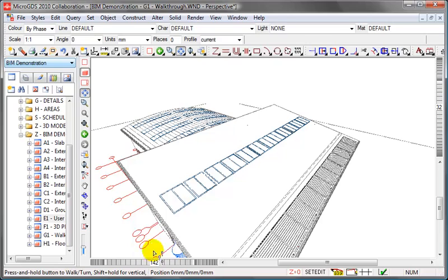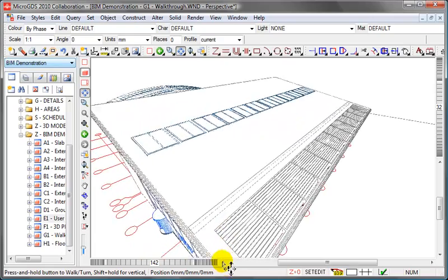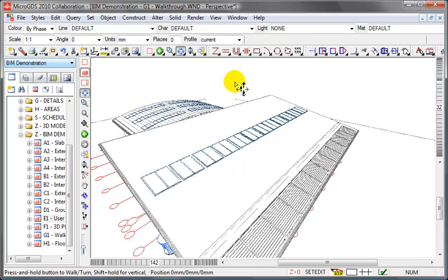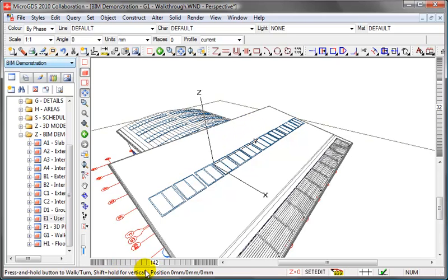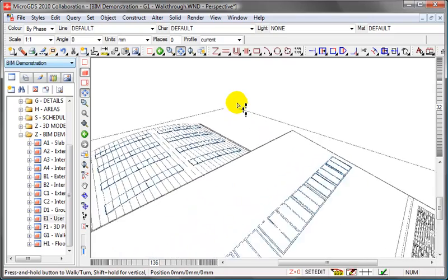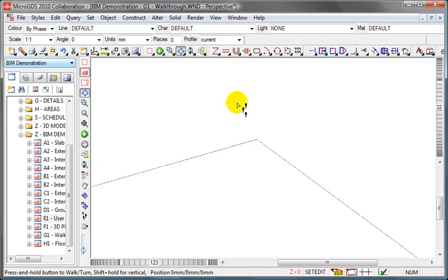And there are modifiers for this command. So if you hold the shift key down and you move the mouse down, you go lower. And if you move the mouse up, you go higher. And there are other options as well. One that's not visible because we're working with a smaller window here for the demonstrations. You can't see all the options. If you hold the control key down, you actually run through the model, so it accelerates the move through the model. So it's a much faster move.